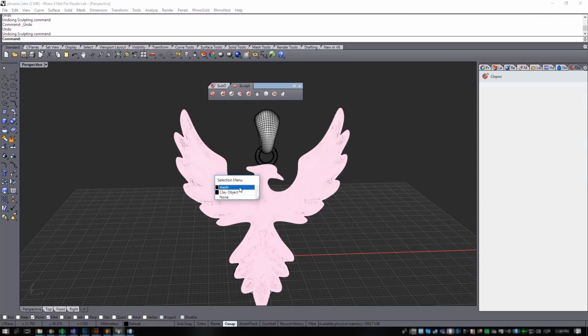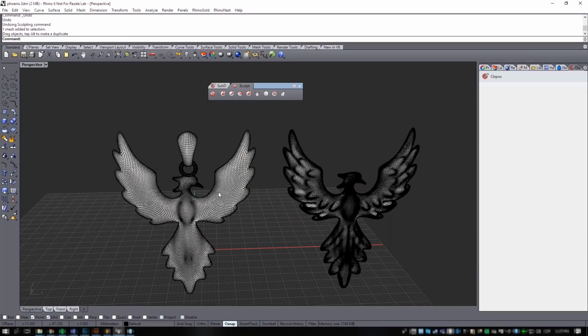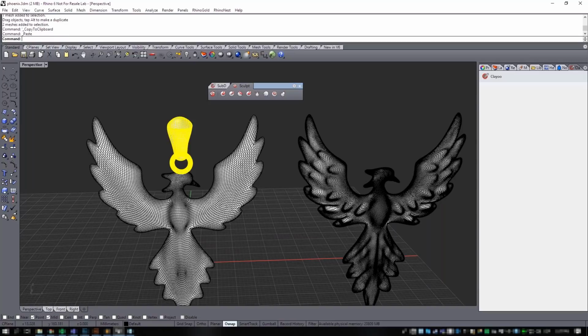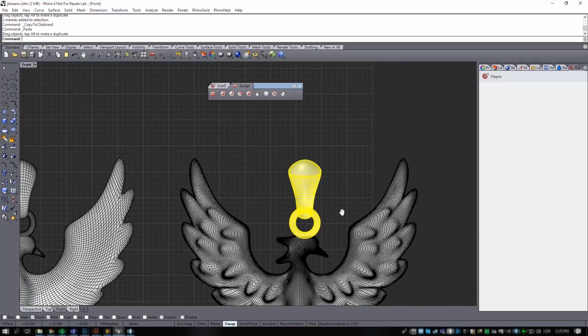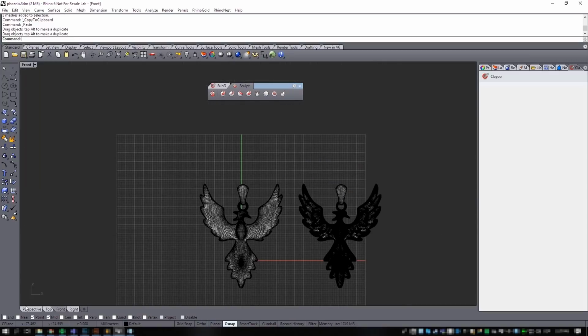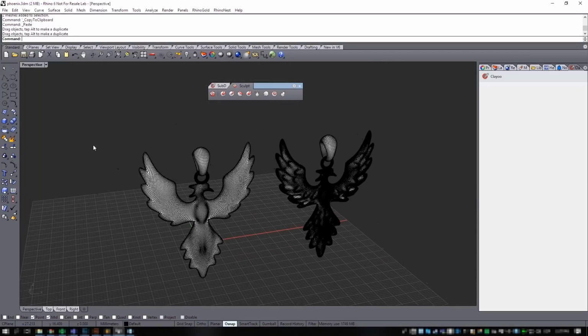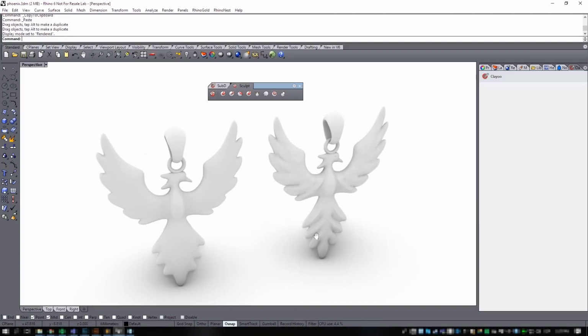So right now in here I have both models. The mesh, that it's the model that we have sculpted, that it's no longer a Clayoo object, okay, and the Clayoo object. So I'm going to select the mesh, and I will move this mesh a little bit. There we go. So I can copy also the veil, Control C and Control V, and from the front view, I'll make sure that more or less the position of the veil it's correct, something like that. There we go. And right now from the perspective view, you can see that if we display it in rendered mode, we can see the differences right now.